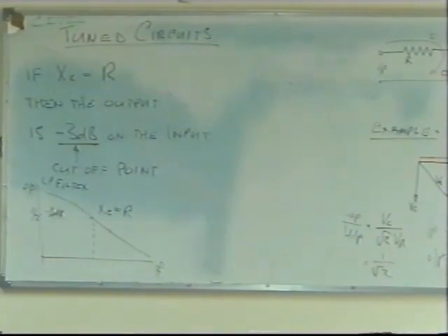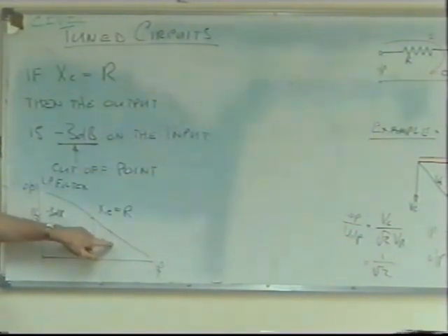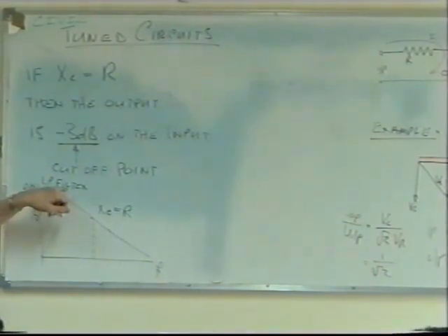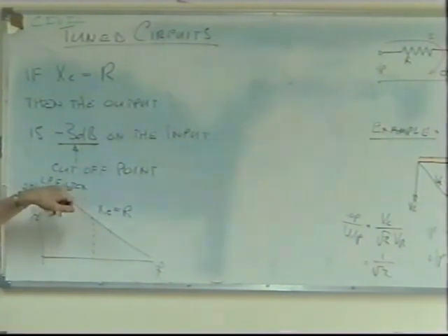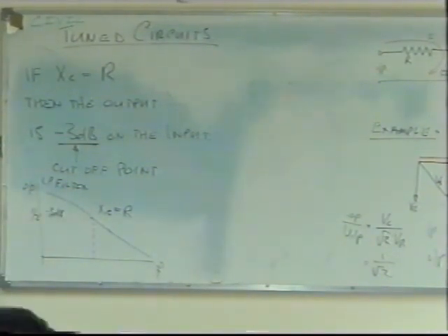Now, it's not very clear as to why that's cut off, but what they're saying is, okay, it's a point in our graph. We say anything above that frequency, the signal is rejected. Anything below that frequency, the signal is accepted. I used these 2 words last week, or the week before last, to describe the cutoff frequency. It's a low-pass filter.